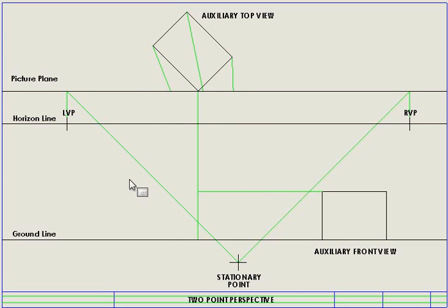Okay, let's get started. I have to make use of the information that my auxiliary front view presents. The information it presents is our height. Remember, when I'm looking at an object from the front and I'm projecting any information across, it would be the height. I only have one set of information. Sounds funny saying that, yet I'm going to be projecting that across to this line that is dropped from this point down to my ground line. I call this line my information bar.